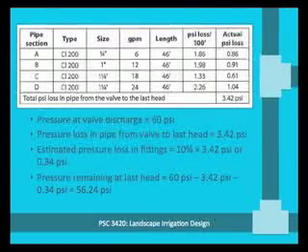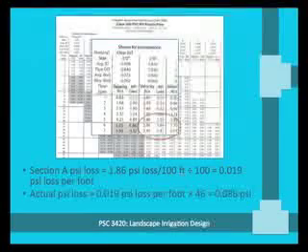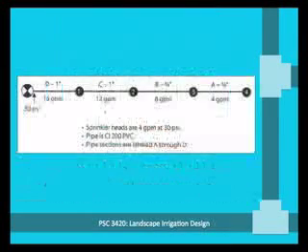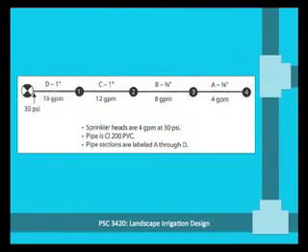And you would just go through each pipe section using that same process, the appropriate chart, the appropriate columns with pipe size and flow rates, until you ended up with the total friction loss for that entire lateral. So here, let's do another example. Again, note that there are different pipe sizes in the different sections of pipe.